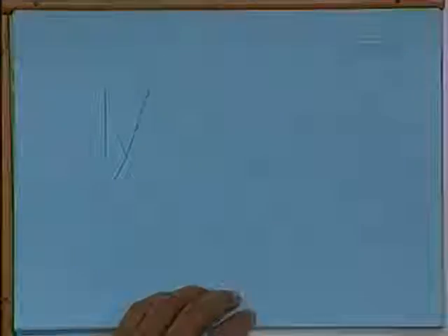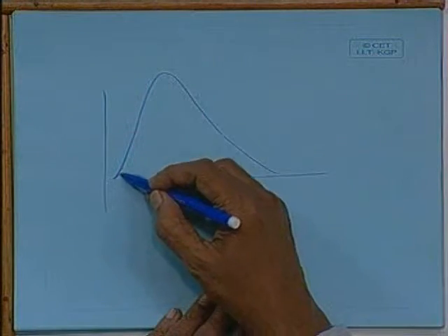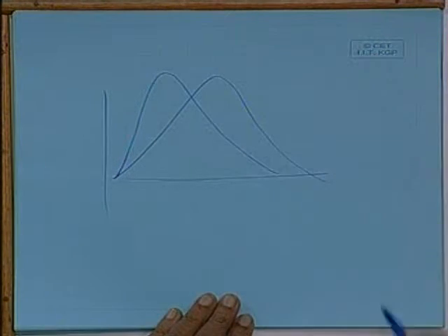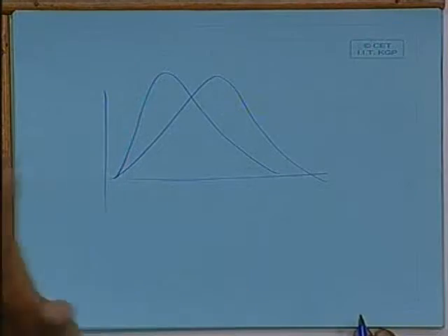Whereas, when you go towards older ships, the curve changes to a normal distribution, that is, thickness diminution is more over a large area, and large thickness diminution is there. You understand? Some of these points led us to look at corrosion and corrosion related stresses, or stress related corrosion.